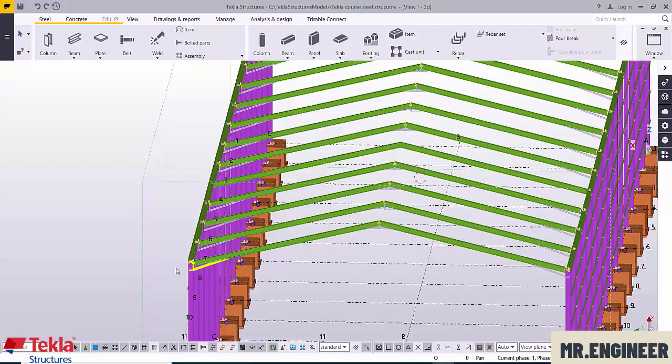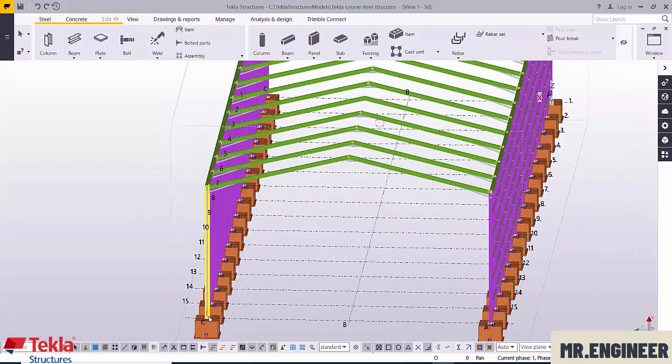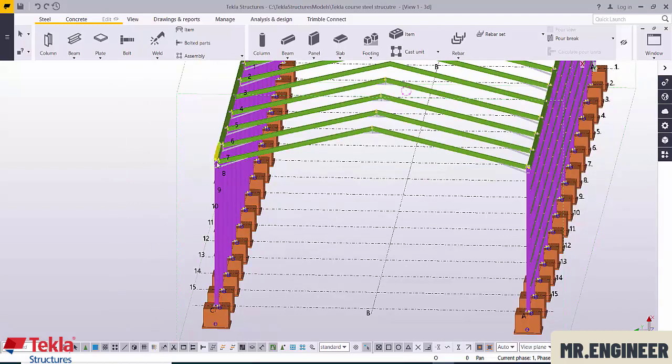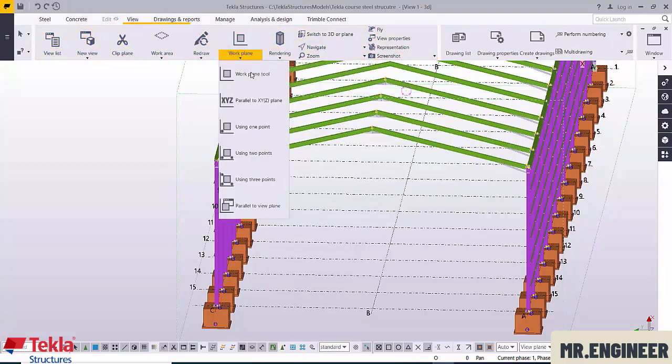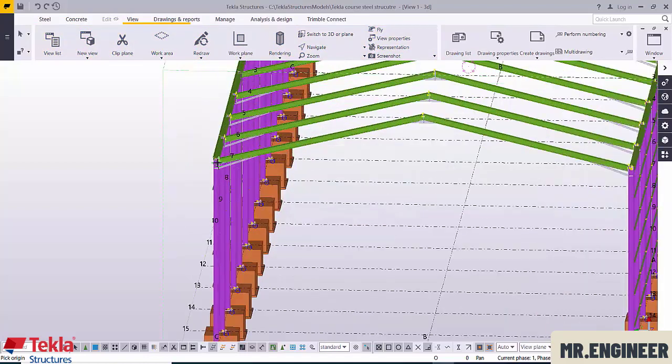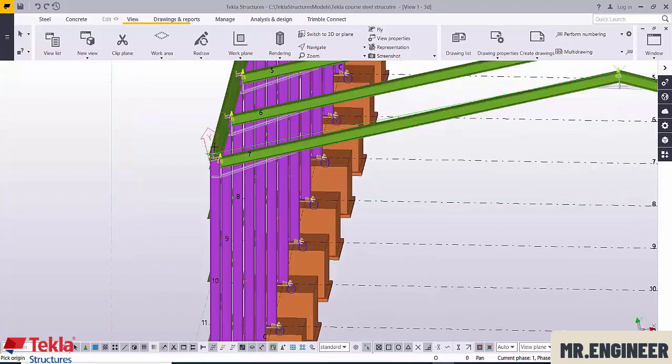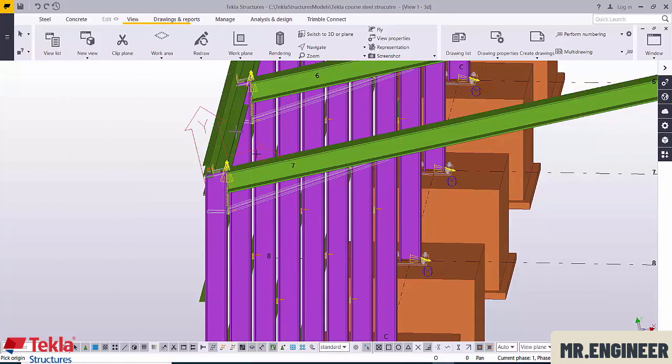What is the method? First of all, we need to create a new axis, XY axis here. So we need to move the XY axis from here, to do a copy linear each 2 meters on this line. So we can go to View, Work Plane, Use 2 Point. The second point is here to here. So now we can show the XY axis is here.